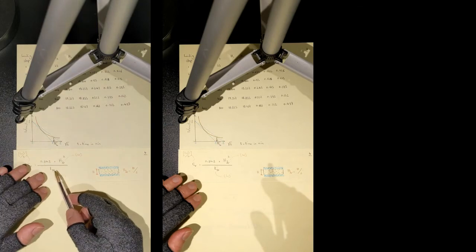So remember, your T sub 90 that you determine from our oedometer test is normally in minutes. So you've got to convert minutes to hours. This is very important. And all your heights in oedometer test are in millimeters. You've got to convert those to centimeters to make use of this equation. What is H dr? Well, this is a constant, and T sub 90, I know already how to determine T sub 90, but let's look into H dr.